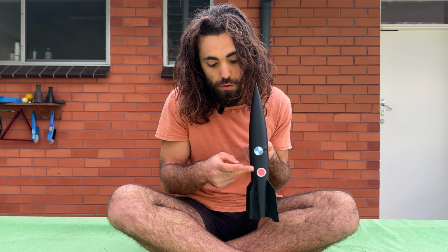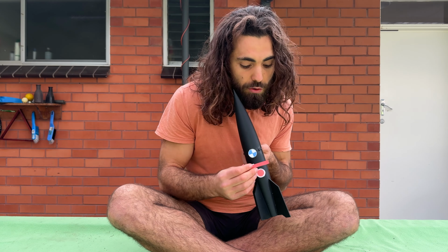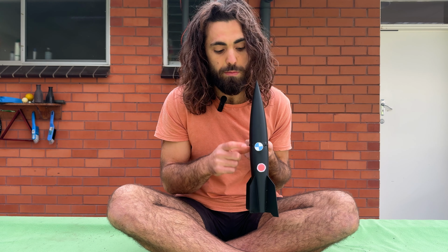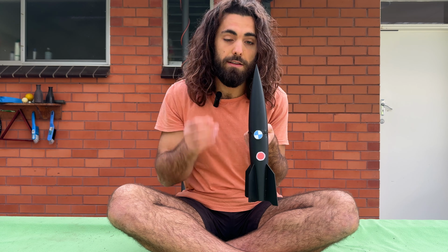So if we just apply this force, it's going to correct the rocket back to pointing straight. Let's say it overcorrects accidentally and this force pushes it too far to the right. Now the right side is exposed and we're going to get a force to the left, and that's going to keep it straight. So long as our center of pressure is always behind the center of gravity, as the rocket gets knocked off course on its way up, it's always going to correct itself back to shooting forwards.